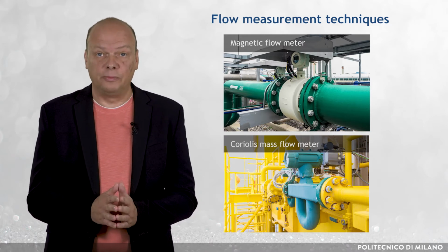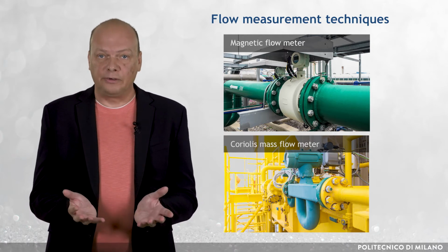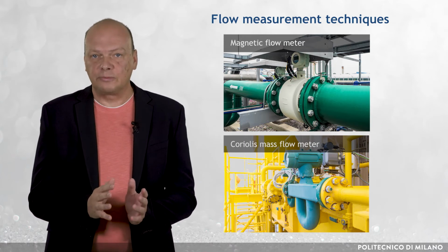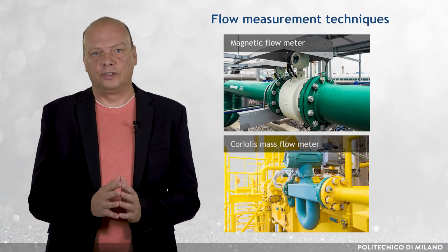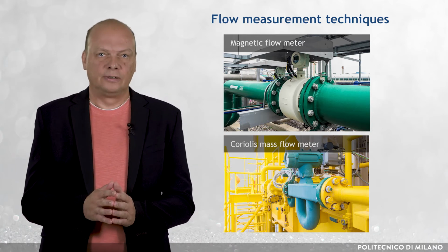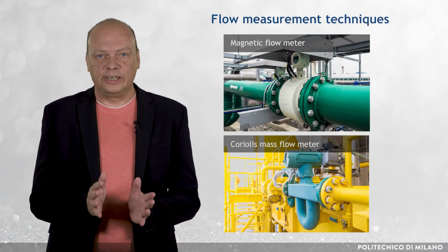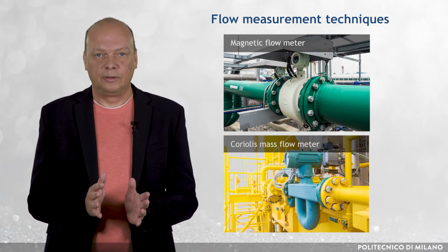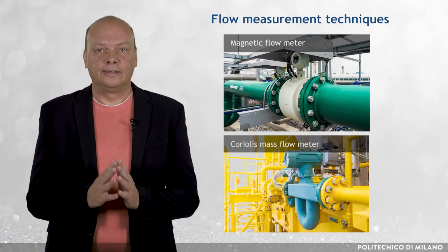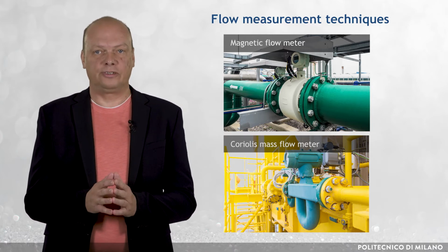The magnetic flow meter should be installed in a vertical pipe if stratified flows are to be tested. The meters are relatively inexpensive and the most often used in both laboratory and field pipelines. Coriolis mass flow meters monitor the density of the substance in the pipe, the volumetric flow rate, and consequently, the mass flow rate through the pipe to a high degree of accuracy.